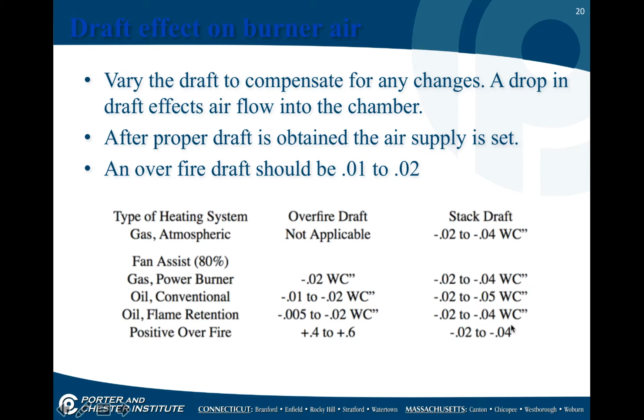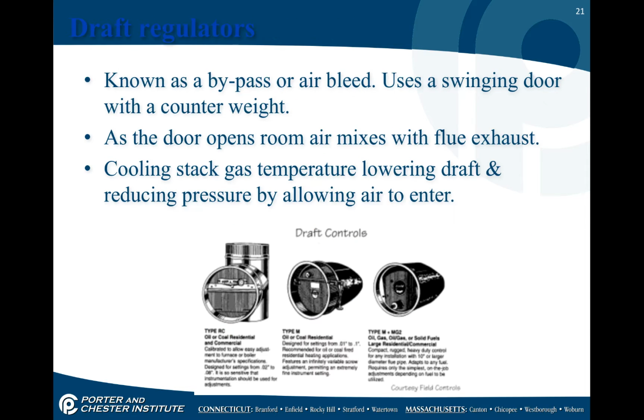The stack draft, which is taken above the furnace or boiler, we really want a negative 0.02 to a negative 0.04. You'll notice that range. I really like to see a negative 0.03 to a negative 0.04. And again, that's all adjusted using the draft adjustments on the draft regulators.